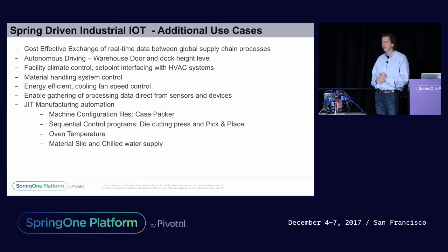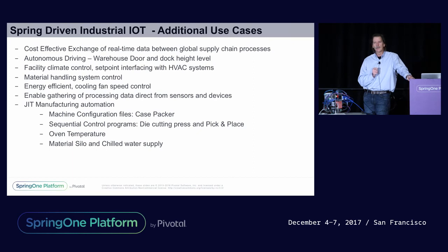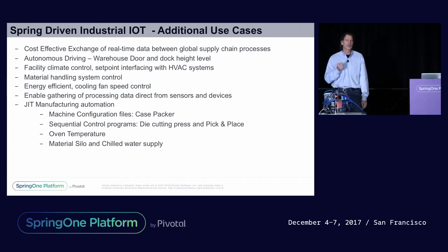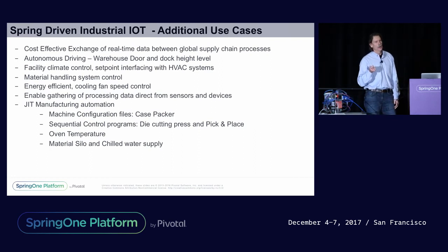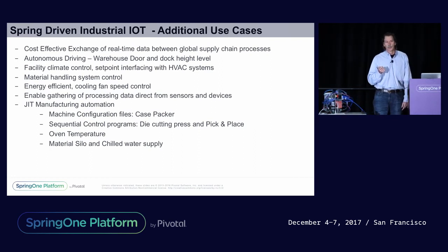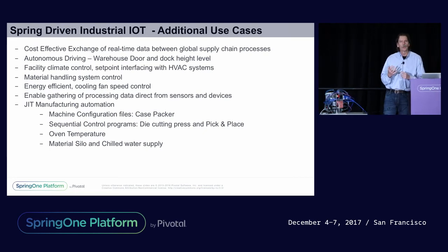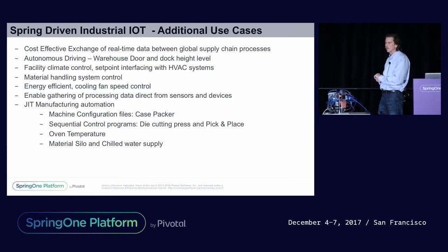Another issue that typically this runs into is the amount of memory in the controllers at that lower level is limited. So when you start talking about a significant number of programs, that can really be an issue because for most recipes on these machines, you have to designate the amount of memory for the largest program that you're going to store. So that means you're limited on a number, where in the enterprise we have pretty much an unlimited amount of storage space.